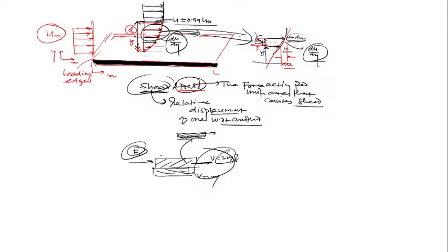is tau. So what we have seen here is that as the fluid particles come into contact with the surface, the velocity becomes significantly less as compared to the upstream velocity, and it can be assumed to be zero for the fluid particles on the surface. Those fluid particles act to retard the motion of the fluid particles in the adjoining layer, and so on, right?